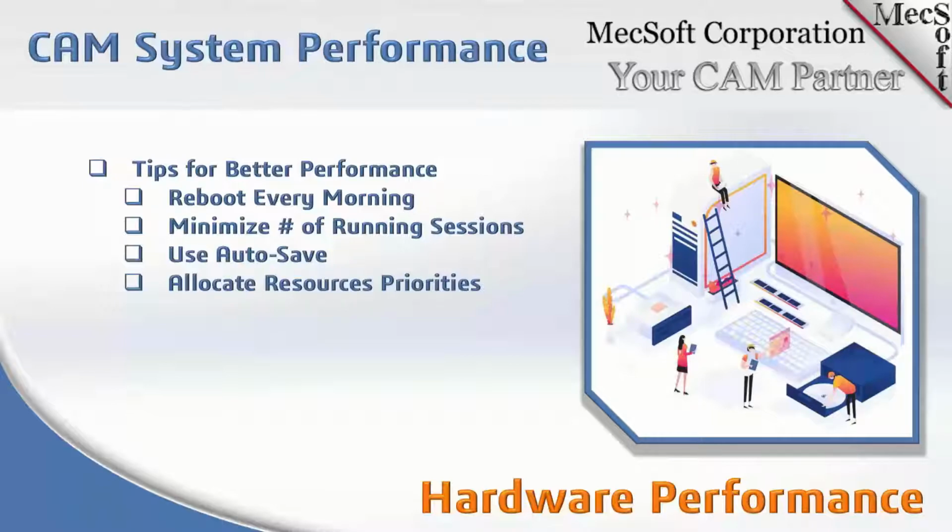We have done support sessions with users who we discover have 7, 8, 9 sessions of RhinoCam running, and they're working on one of them. Every one of those sessions takes system resources away from the session that you're working in. So try to get into the habit of only running one session at a time, and that'll be your optimum performance.